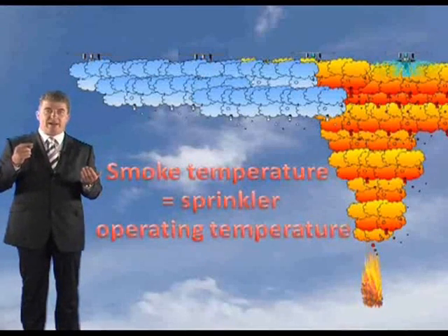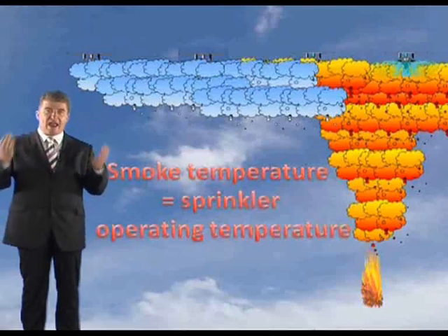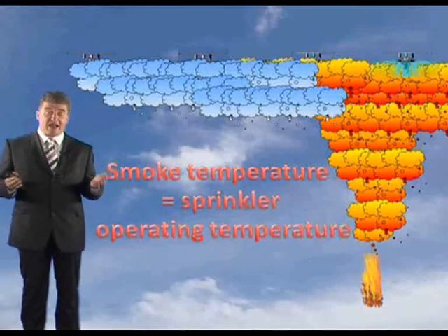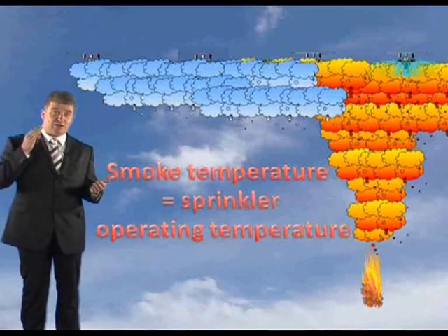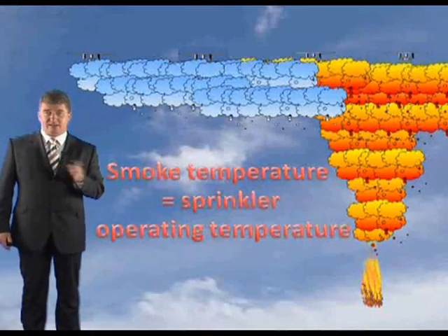What's the sprinkler operating temperature? First one goes off, cools. Second one goes off, cools. Then you're looking at, it's not going to be much far off the actual sprinkler operation temperature. That's a guide. That's if the ventilators are natural ventilators.